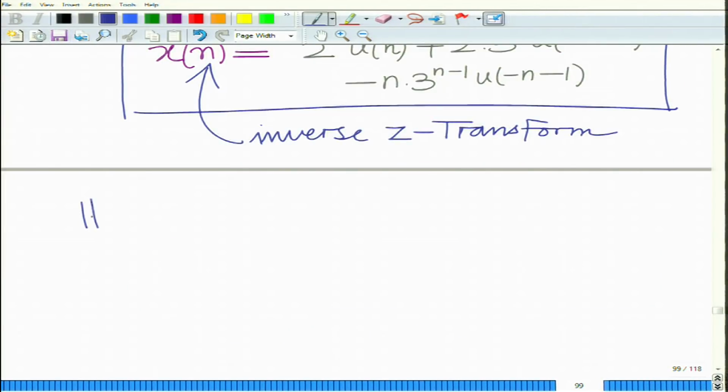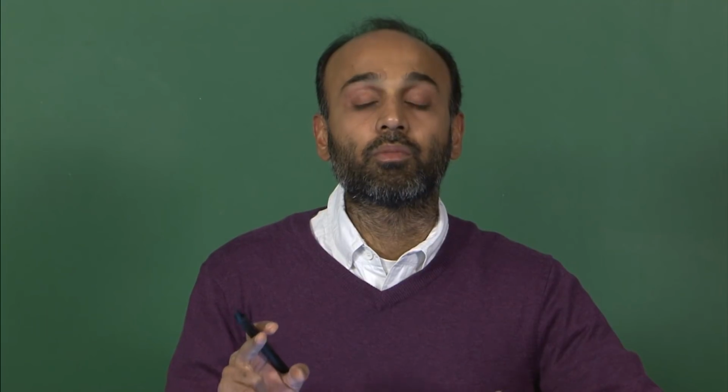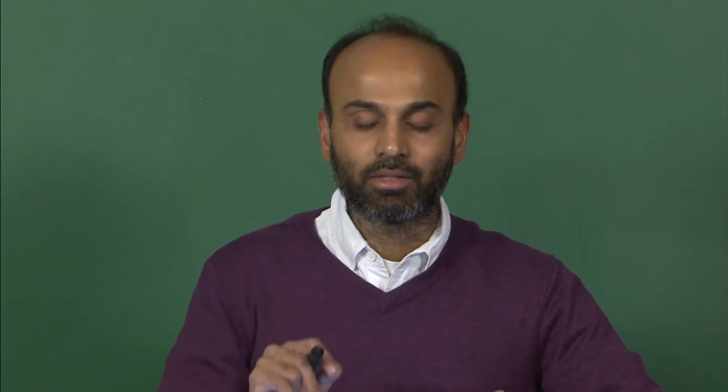Okay. So, this is the inverse z transform. So, we have constructed the inverse z transform of this rational function. Remember, we started with a rational function of z which has a pole of multiplicity greater than 1, a pole of multiplicity 2 at z equal to 3, alright, and that is basically the inverse Z transform, which we have derived by first constructing the partial fraction expansion and then constructing the inverse Z transform of each of the terms in the partial fraction expansion. Okay. Let us look at another example.